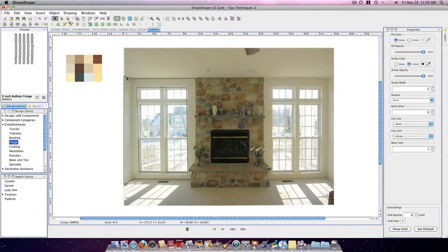Click on the first cubic Bezier line that you drew and then the second one. Click on drawing, path operations, subtraction, and watch what happens. There you go. It will fill, okay, but it will cut out or subtract the window. Isn't that neat? Then you can actually click on stroke color if you want, and it gives a very light stroke color.